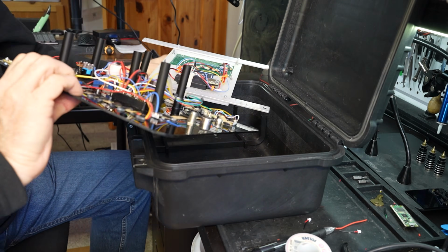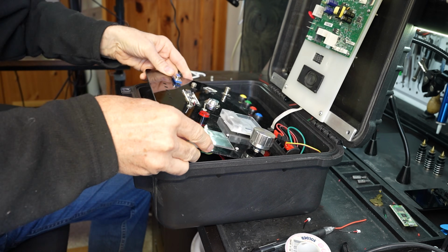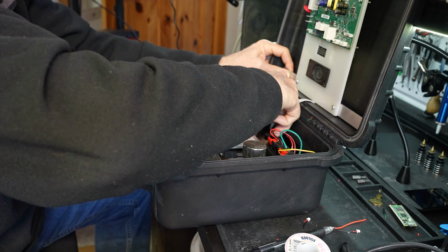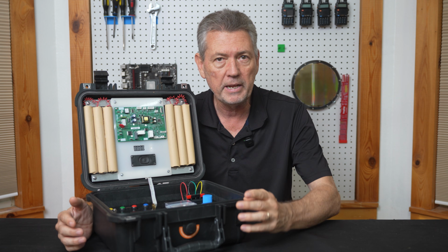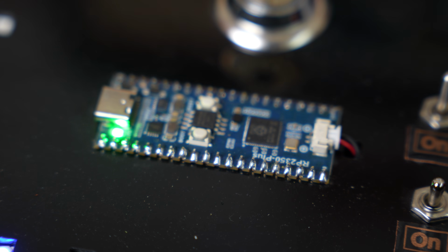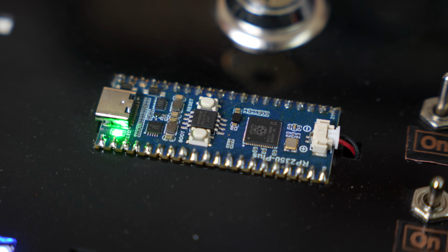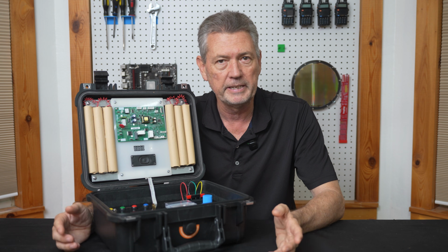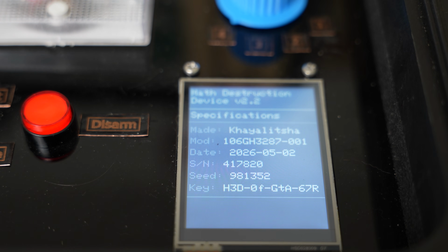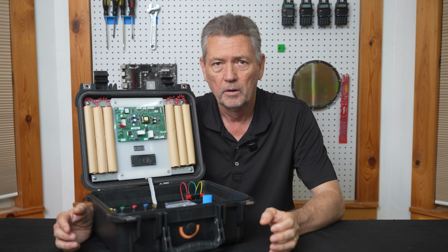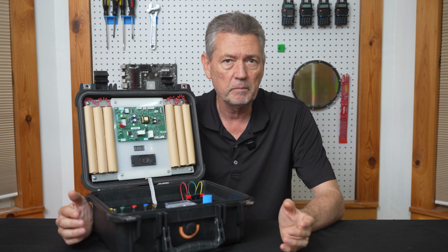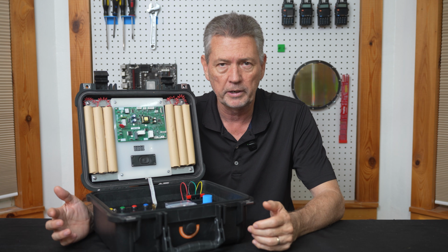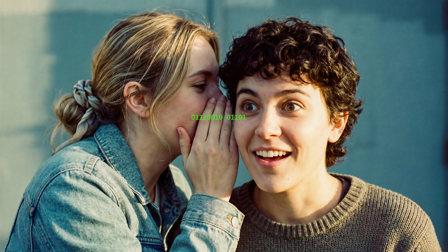With the hardware mounted to the panels and all connected up, it was time for the hard part, making it actually work. We're using a 2-brain system here. The main game master is my favorite, the Raspberry Pi Pico RP2350. The second brain is an ESP32 built right into the smart touchscreen display, which will generate visual clues and actions for the player. To get them talking, we wired up a simple UART connection so they can whisper secret binary codes back and forth between themselves.